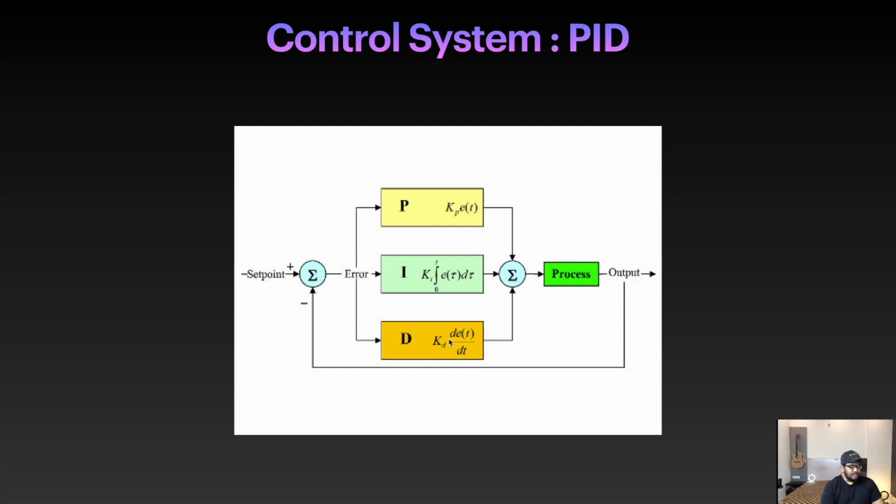So this looks very intimidating, but when we actually understand it, we take the error signal, multiply it with Kp, integrate it with Ki, and differentiate it with Kd. What we get is a sum of the values which the flight controller generates to compensate for the error. So that is the entire concept. You just need to find the error signal, the value of the error.